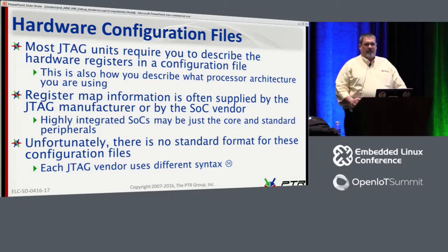The big problem, the long pole in the tent with JTAGs, is the hardware configuration files. The hardware configuration files have to describe all the registers of the processor core. We also have to, in many cases, describe all of the registers of the peripherals that happen to be loaded on the motherboard. We have to describe whether they are 32-bit, 8-bit, 16-bit, read-write, read-only, write-only registers.